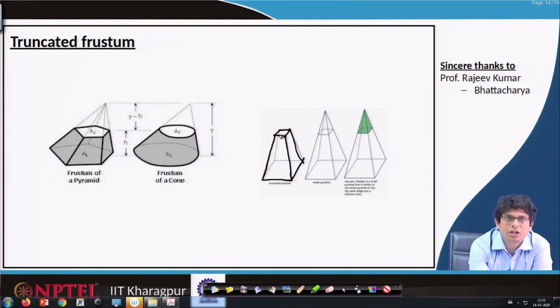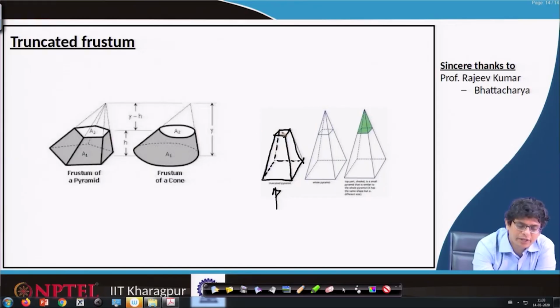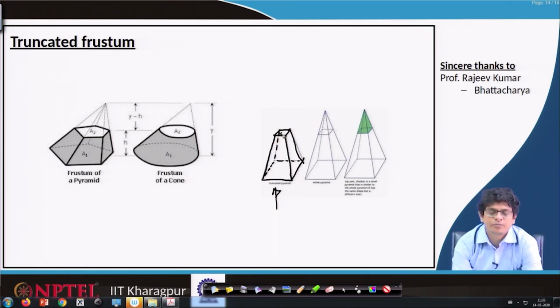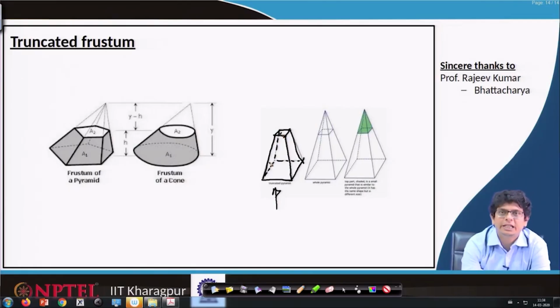Any lines which are not visible and perhaps at the back side, we usually show by dashed lines. When we are looking from this view, the back side line we can't really see, because it is a solid object, it is not directly a transparent kind of object. So, in that case we will show it by dashed lines.